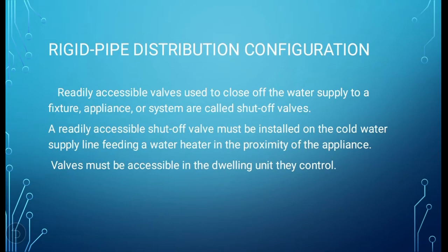In multifamily installations, single or multiple shut-off valves must be installed in each dwelling unit so water to the unit can be shut off without interrupting the supply to the other units. Valves must be accessible in the dwelling unit they control.